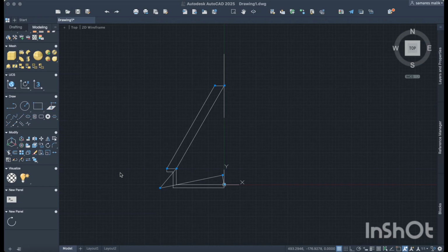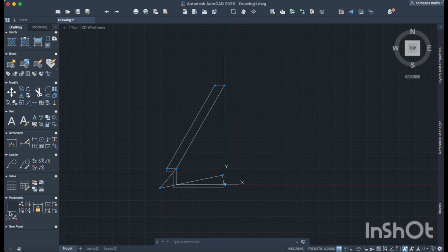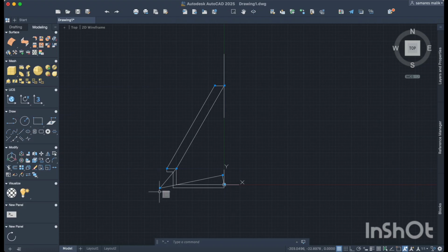We have used AutoCAD constraints, going to the parametric modeling tools. Using parametric modeling in AutoCAD, we have synthesized this model, and to show the revolute joint, we have made the endpoints of two linkages coincident. This is how we showed the mechanism.